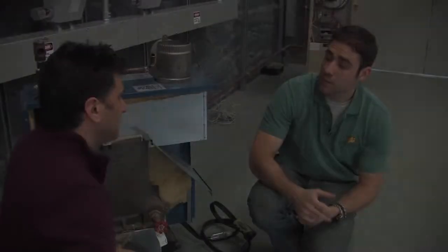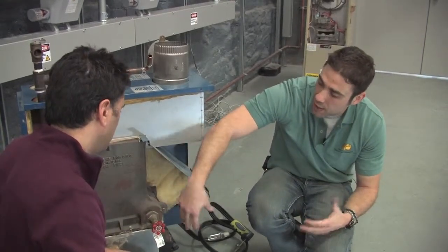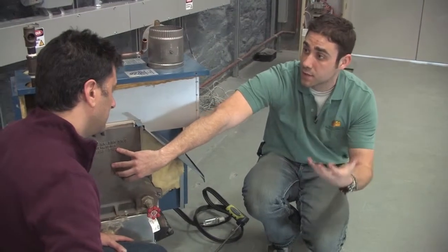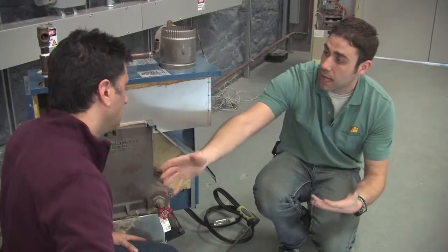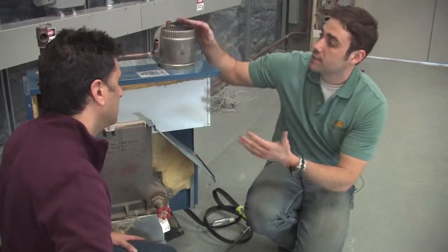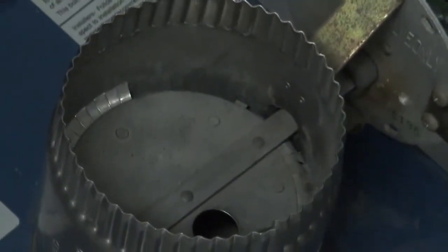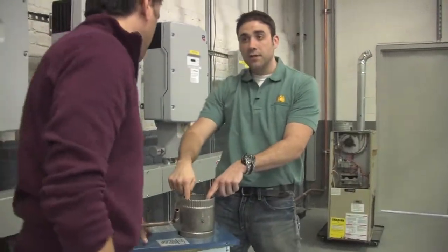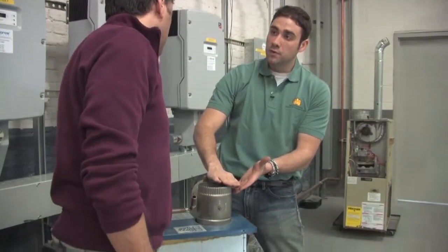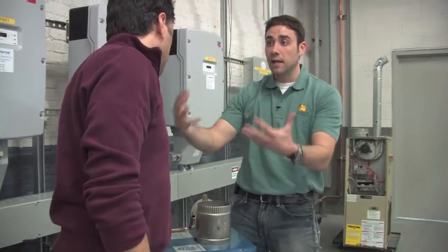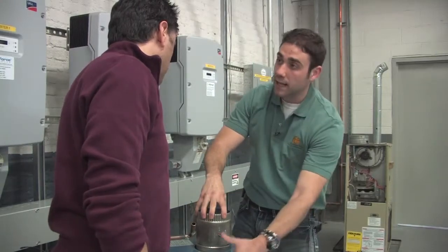All right. Okay, so since this boiler is made out of cast iron, the heat exchanger, there's a lot of thermal mass in here. So when this boiler fires and we heat up this cast iron and the cycle is done and the house or the apartment is satisfied, we still have a lot of heat stored inside this cast iron. So what will happen is we'd have a little efficiency measure we put inside this. It's a flue damper that goes in the top, right, as the outlet of the heat exchanger. So what this will do is, if you look at the top, you can see a little damper in here and it's closed up. So when the system is off, to prevent off-cycle losses, this damper will close and it will stop that air from going in, getting heated up by the cast iron and working its way out. So you will cut down on those standby losses. This way we don't cool off that cast iron.